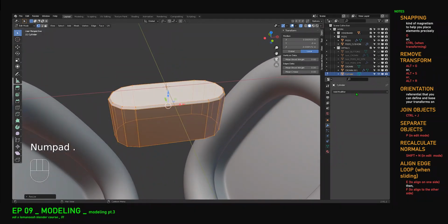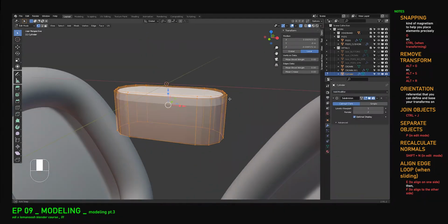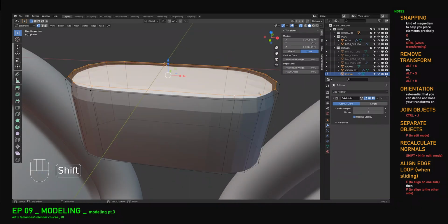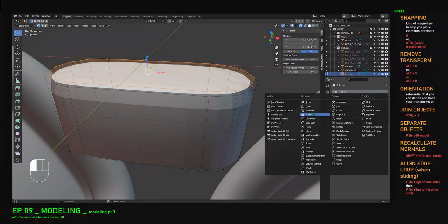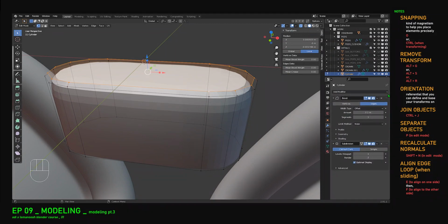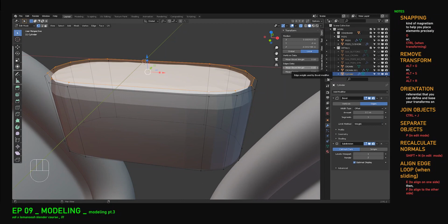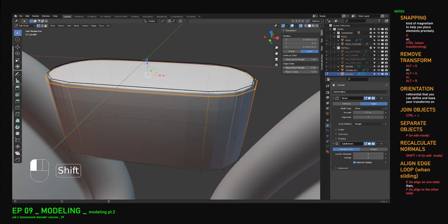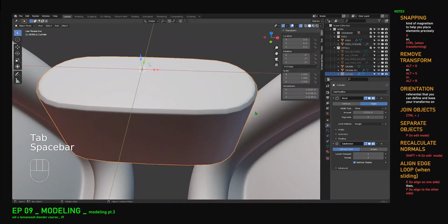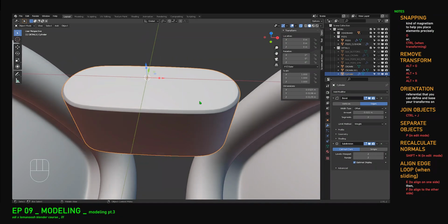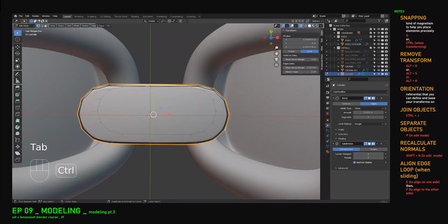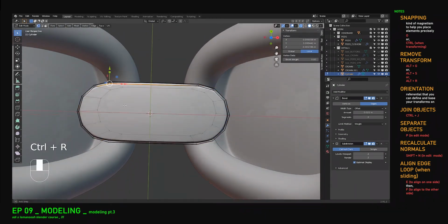And this time we will add some subdivision surface. And we will also add a bevel that we want to put there. And we want to do it with weight. We want to put some weight on this one and on this one. We want 2 divisions, smaller bevel. We know it already. Shade smooth, 1 more division. Not so bad. And here we add, let's just join those.